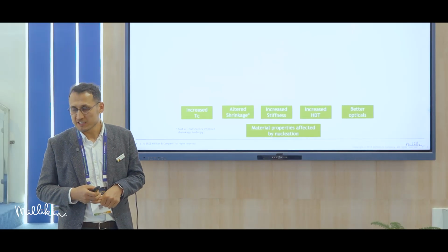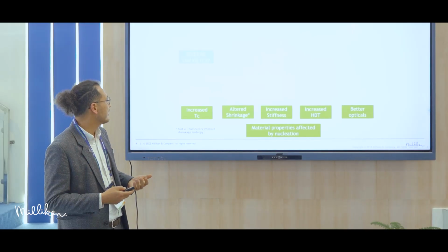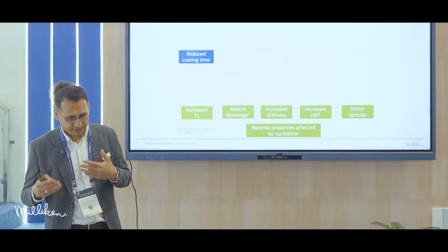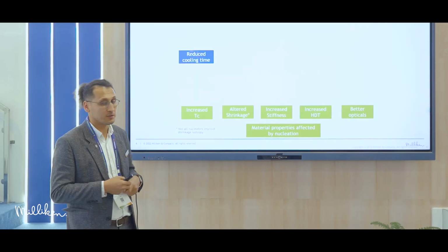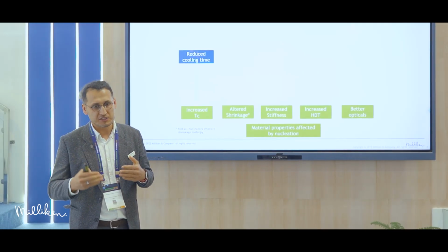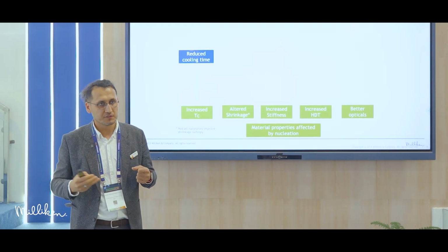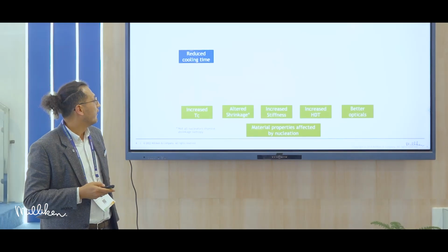It increases TC significantly. Increasing TC, what does it really mean? Increasing TC normally depends on the conversion technology. Normally it means it will reduce cycle time. It reduces the cooling time. That means the cooling of the part starts earlier, and the parts get to the final form in a faster time.